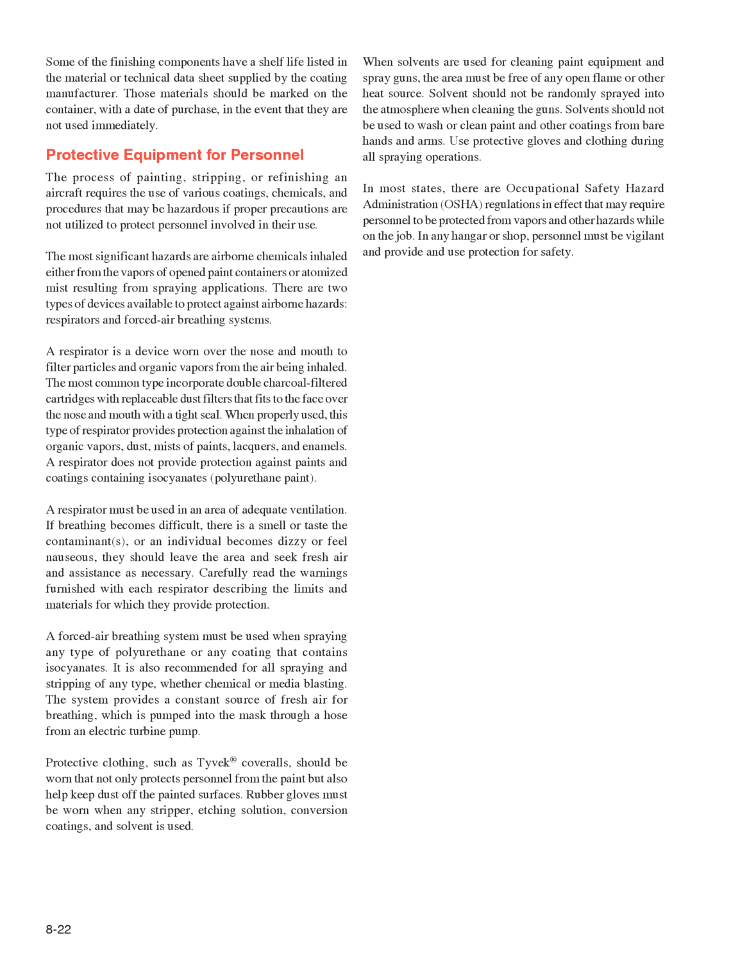If breathing becomes difficult, there is a smell or taste of the contaminants, or an individual becomes dizzy or feels nauseous, they should leave the area and seek fresh air and assistance as necessary. Carefully read the warnings furnished with each respirator describing the limits and materials for which they provide protection. A forced air breathing system must be used when spraying any type of polyurethane or any coating that contains isocyanates. It is also recommended for all spraying and stripping of any type, whether chemical or media blasting.